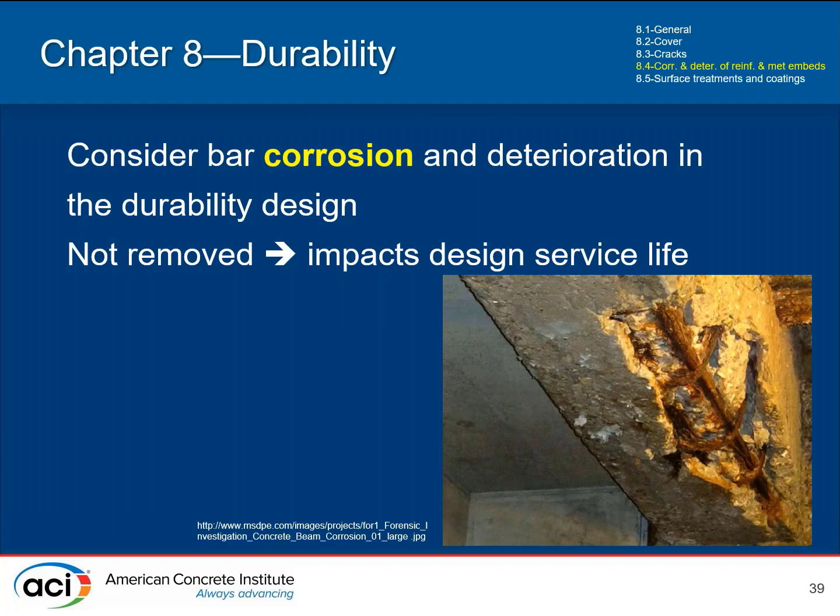So corrosion, hopefully you're all familiar with it. It's rusting of the bars, the rust expands, it'll pop off the steel, you get a spall. That's fundamentally the corrosion process. It's due to chlorides, it's due to carbonation, not really going to go into that here. That's not the objective of this presentation.